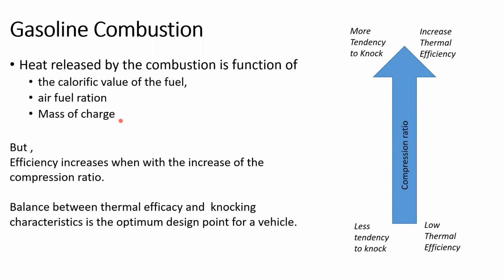So for a lower engine capacity, adding a forced induction system increases the mass of charge, how much air is going inside the air fuel mixture. In order to maintain the air fuel mixture ratio, you need to add more fuel, again more power.